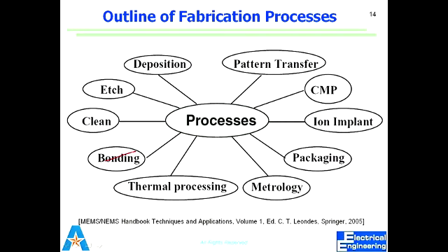But we use them to transfer the pattern onto a photosensitive material which we have coated on a wafer. We expose it with UV light, a specific, very, very precise wavelength, and we wash this coating in a certain chemical called developer, interestingly, because that's exactly what it is doing, developing. So it removes that coating from the exposed area or unexposed area, depending on whatever combination we use. But in any case, we will get the pattern transferred.